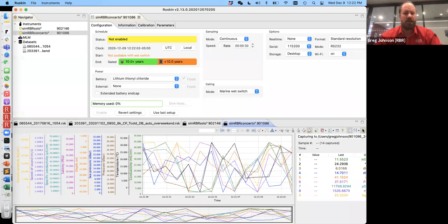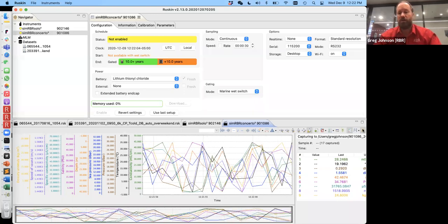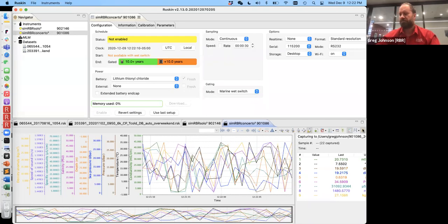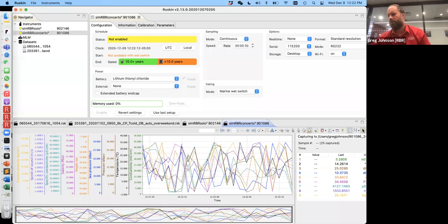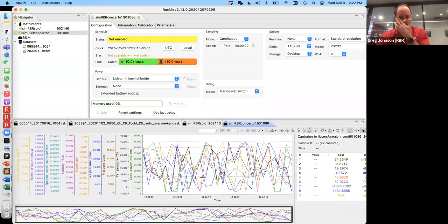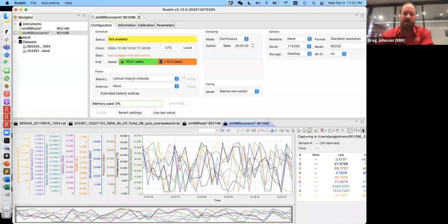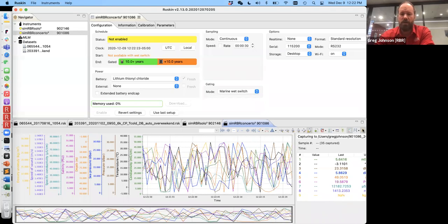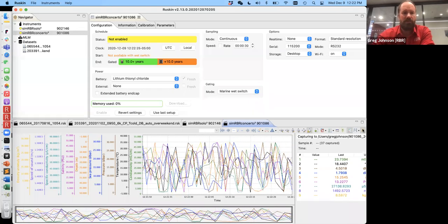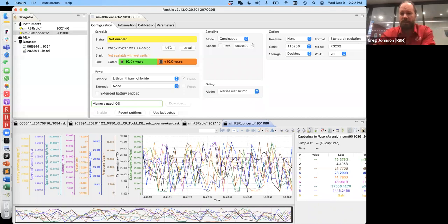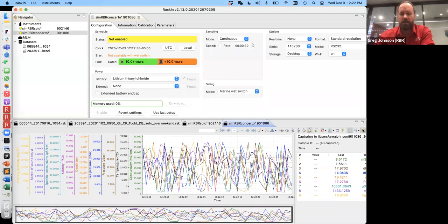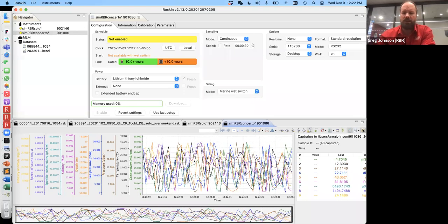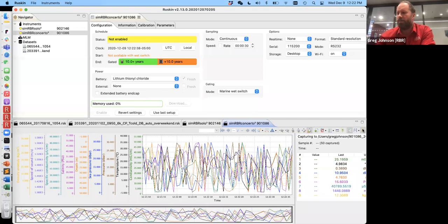But when you have the instrument connected to the computer, and it could be over Wi-Fi or USB or serial direct connections, and we do in fact have Ethernet available as well. If you've got an Ethernet dongle, then you could get live readout from some tank, for instance, that you're interested in monitoring. But it might be a very long RS-485 cable that's in the middle of Lake Tahoe, and you'd like to see that live data as well. Ruskin will let you do this, or you can take that data that's coming over that connection and capture it in your own streaming program as well.